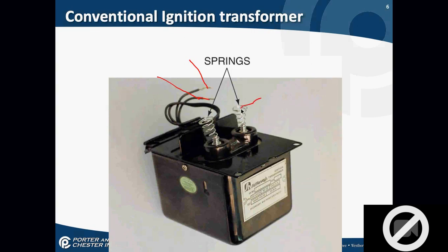Then I'm going to go from there to there. I'm going to put one lead on this spring, one lead on this spring. What should I get? You should also get some numbers, shouldn't you? Is it going to be greater or less than the number that's on the other side? Greater. Yeah, because I'm going to have more windings because it's a step-up transformer. Should I have 0? No. If I have 0, I have a direct short.